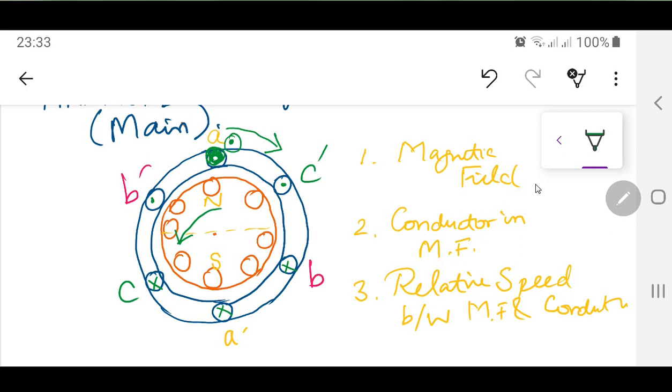So what is happening or telling you that there is a cross and dot formation. Now you can go through this one using your right hand rule yourself. So right hand rule, because this is for the generator. So you have the 3 fingers over there, so you can point out in the relative velocity vector direction, this is that B over there, and certainly you can find out the direction of induced EMF E inside this one.